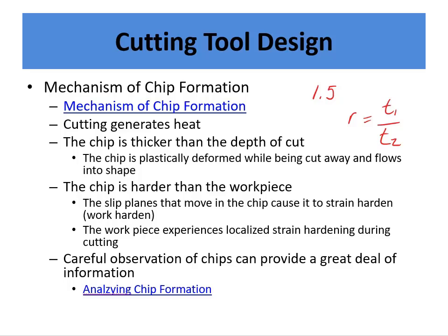So if you're doing any sort of cutting process, it's a really good idea to capture your chips and then analyze them afterward and see how things are actually working out. Because most of the time when you're cutting, you're using some recommended speeds and feeds, but they may not be optimum for your given setup. So one of the best ways to analyze what's actually happening is to capture your chips when you're done, and then look at them and deduce from them what's actually occurring. They'll tell the truth of what's going on.